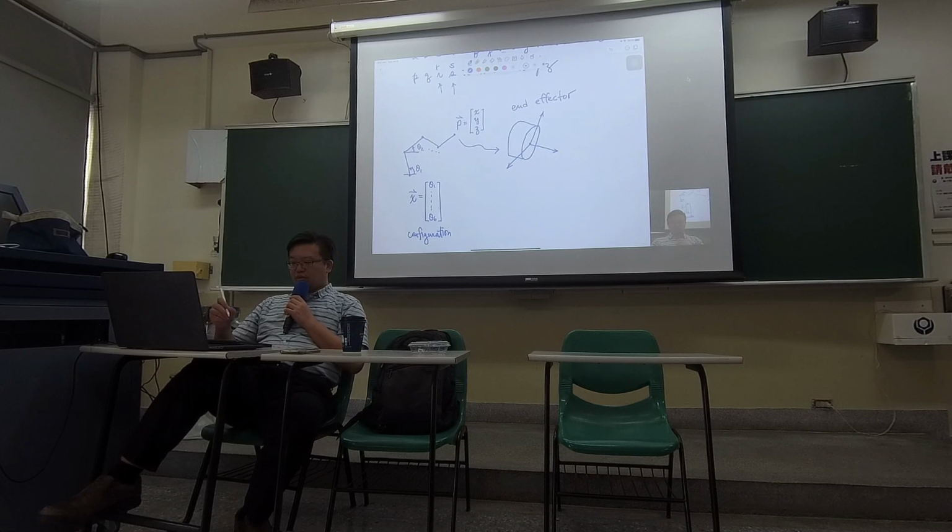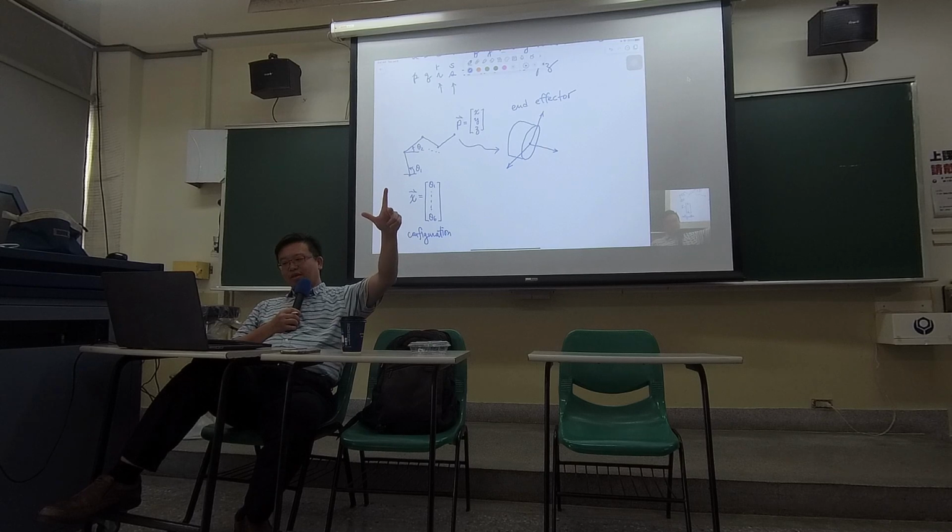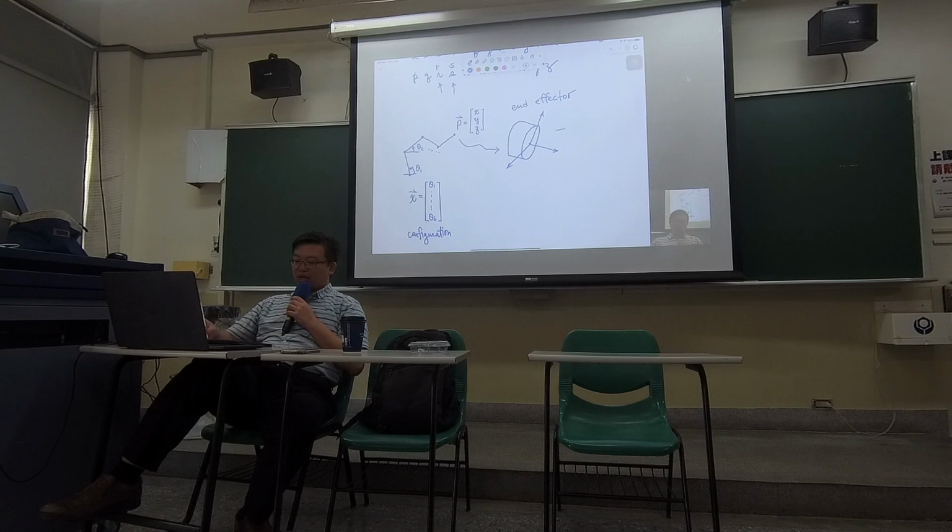So that frame, if you only focus on the XYZ, then I cannot tell the difference if I spin around certain axes. So in fact, you are controlling not only the coordinate of the end effector, you're also controlling its orientation. So in fact, P is like 6 degree of freedom as well.